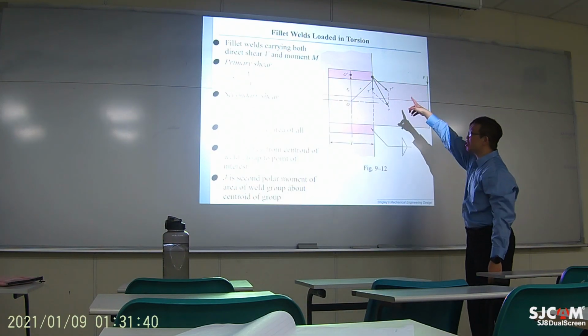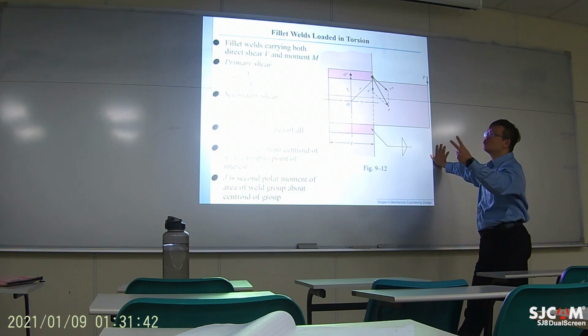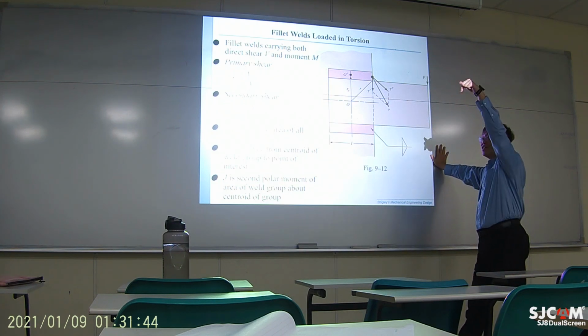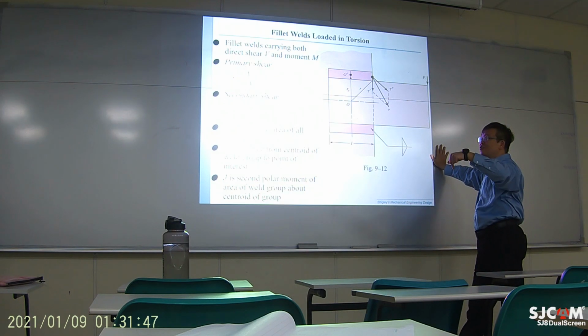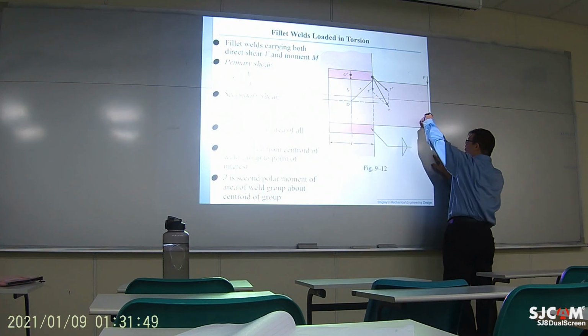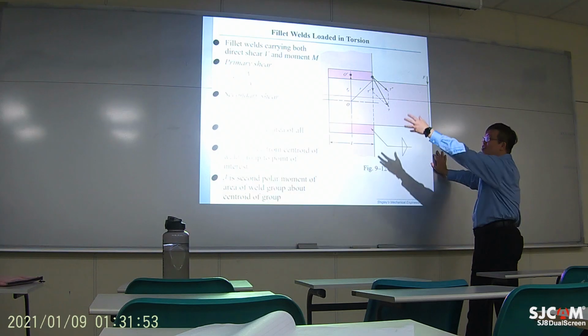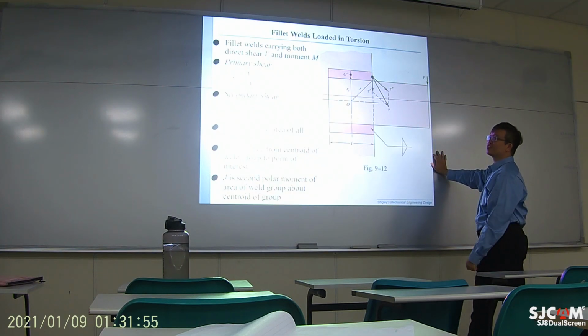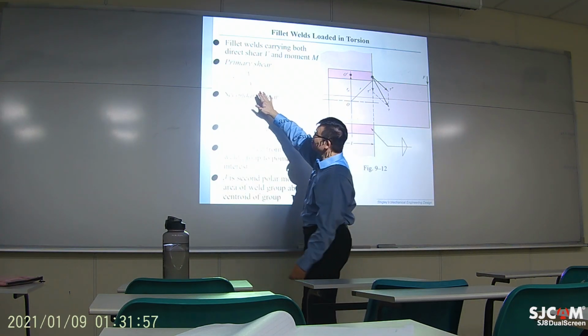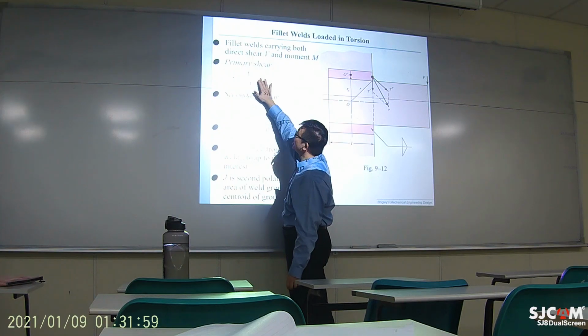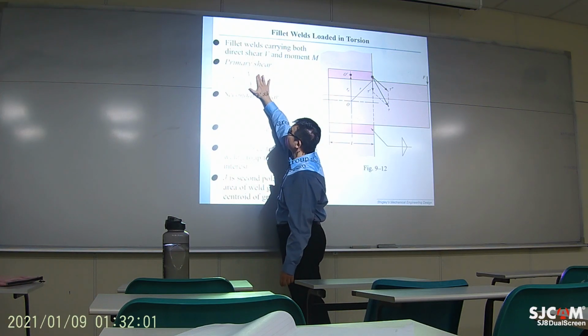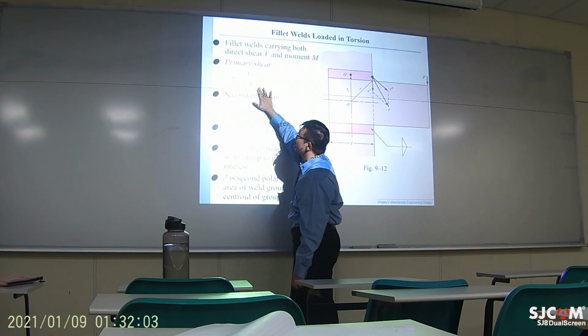Okay, so that particular point has two parts of the shearing stress. One is along the loading direction. The other one is along the rotational direction. So right here, the first part equals the shearing force over the stress area.